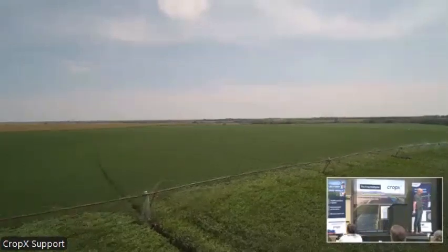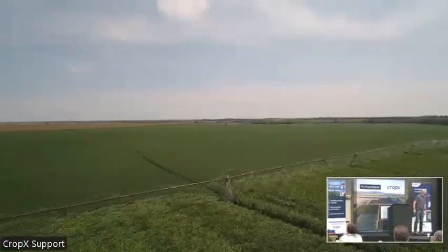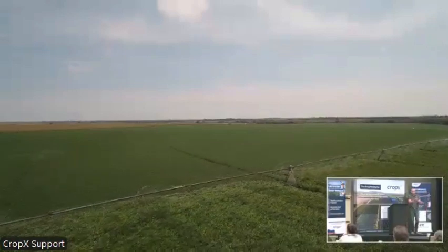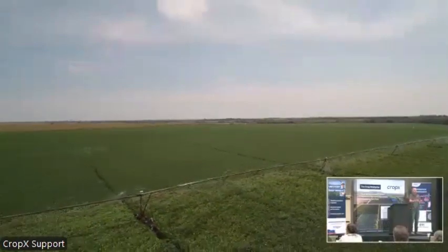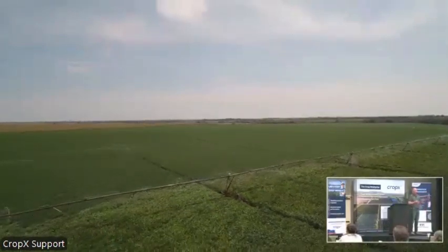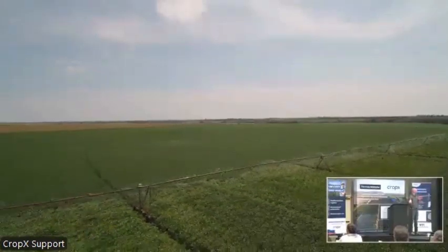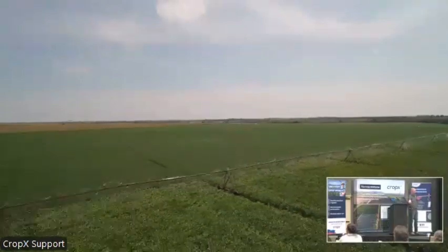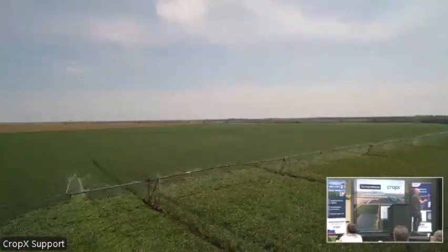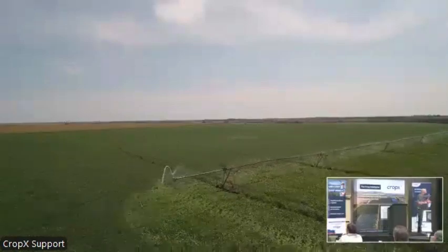That big leak you guys saw there, what about right there at that boot or at that gasket, right? All these extra flows that are being generated here that we didn't account for moved us so far to the right, we can't generate the right amount of pressure. And it gets worse the farther we get out. The farther we get out, the worse it gets. And then you'll get out here and look at that end gun there.